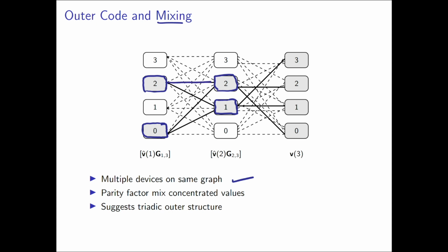We can take this to much larger section sizes. Suppose that we have k non-zero entries per section. If a parity section is attached to 2 information sections, then there will be k^2 highly likely parity patterns. Likewise, if the parity section is attached to 3 information sections, then there would be k^3 highly likely parity patterns, and so on.